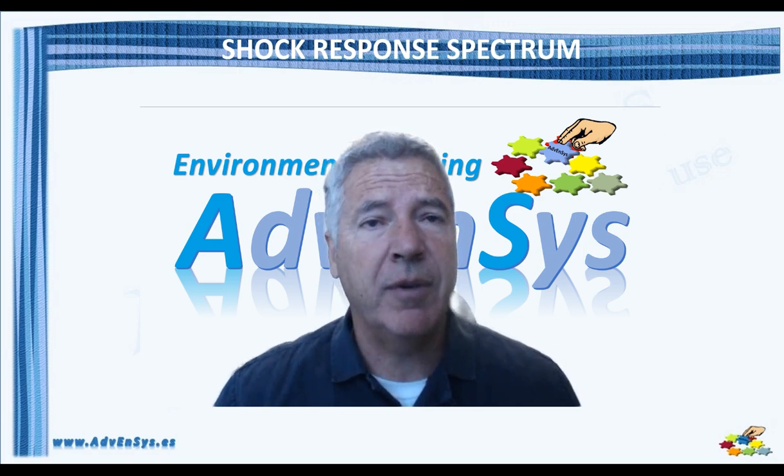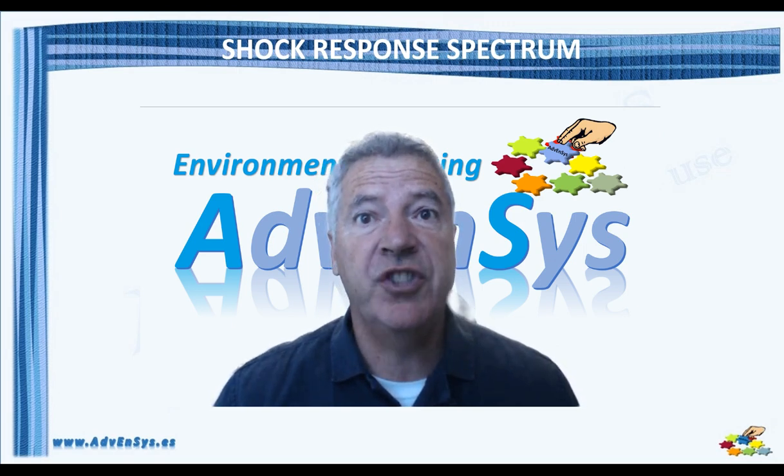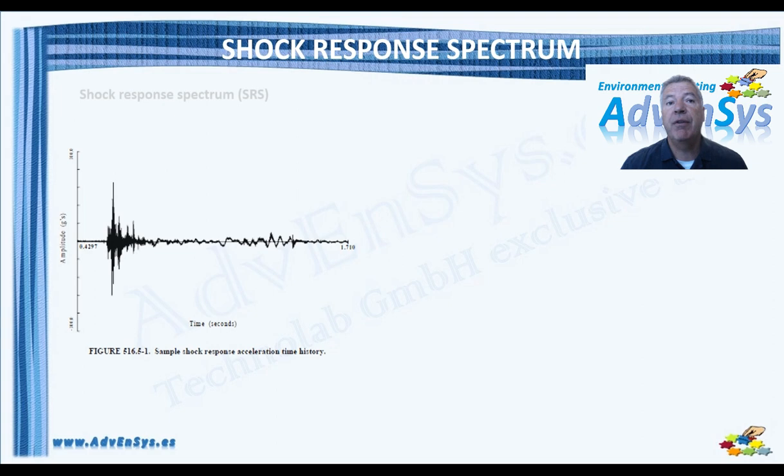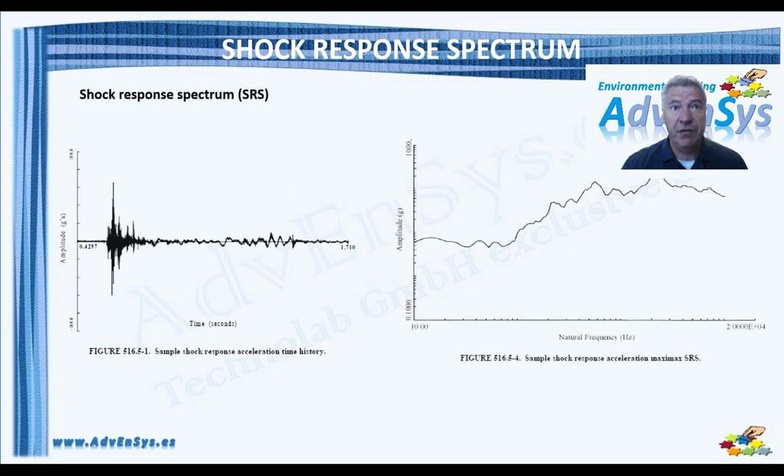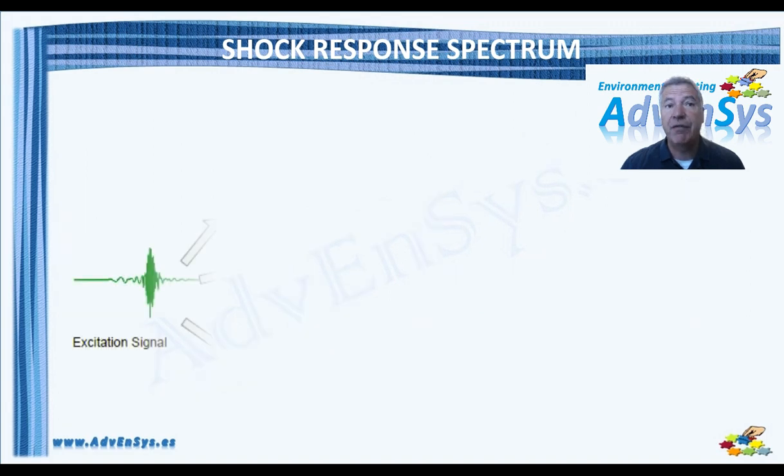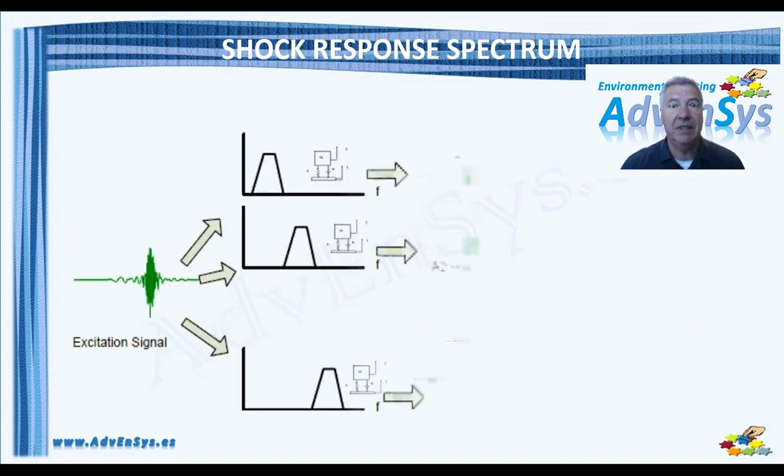Today we are going to talk about two parameters directly involved in pulse synthesis from a given SRS reference, T-e and T-E. From shock response spectrum theory, once the Q factor is fixed, we know that the transient acceleration time history has a unique damage signature plot called SRS that represents the energy content of that time history trace at different frequencies within a frequency band.